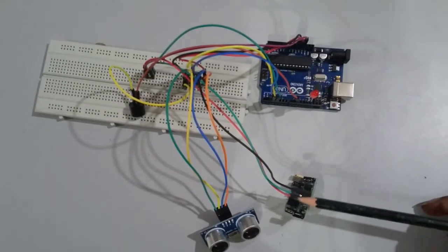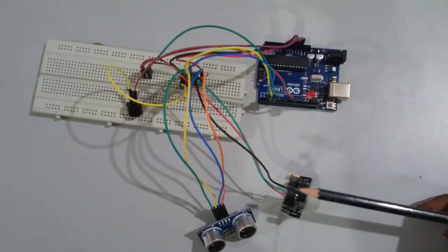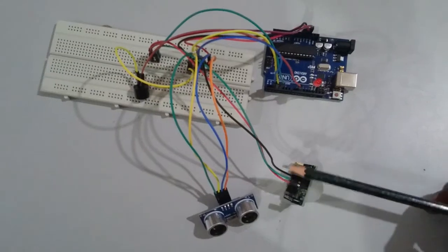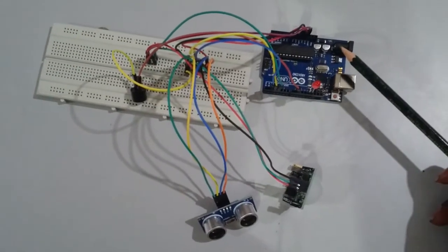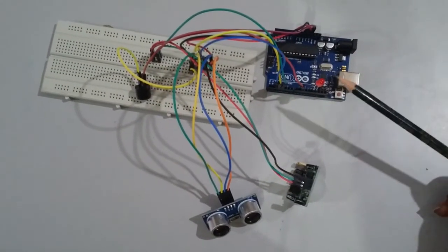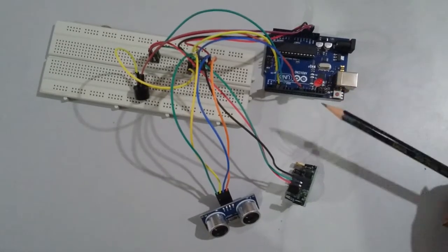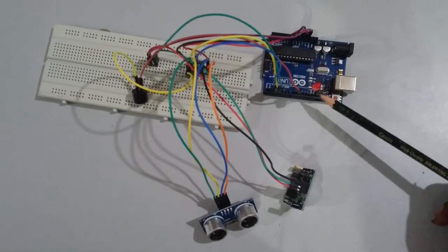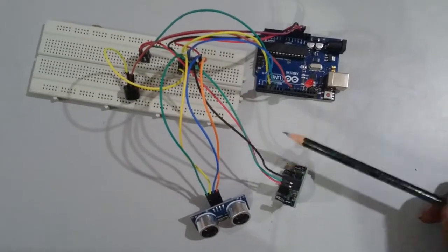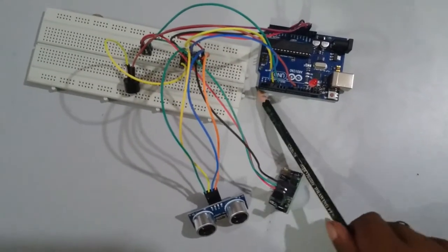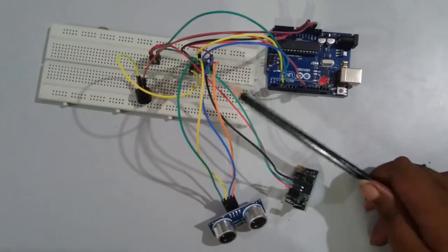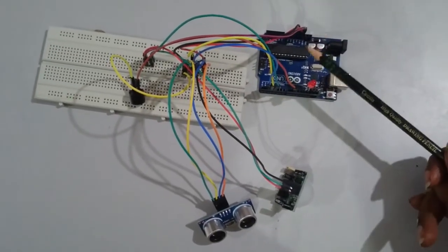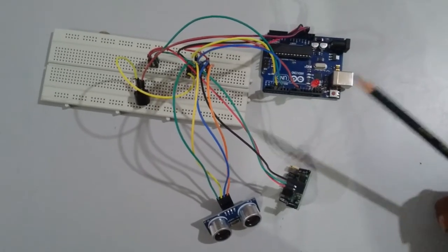Now the Vout pin of the PIR sensor is connected to pin number 4, and ground and VCC go to ground and VCC of the Arduino board. We have connected an LED at pin number 13 and connected it with ground in the Arduino board. We have also connected a buzzer at pin number 10 and its ground is connected to the ground of the Arduino Uno board.